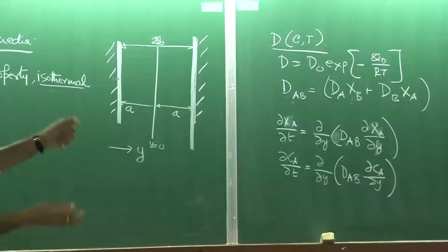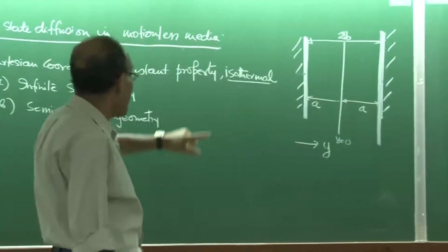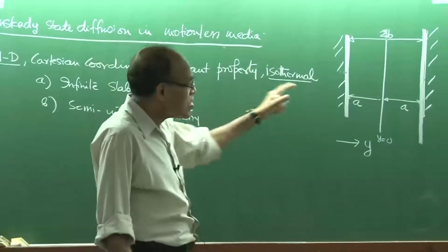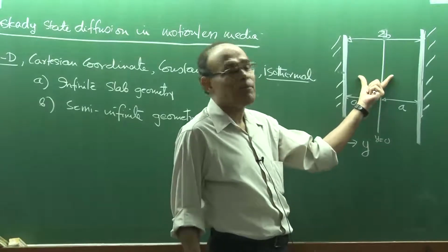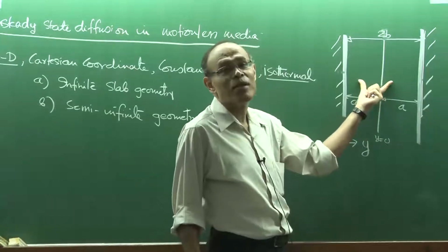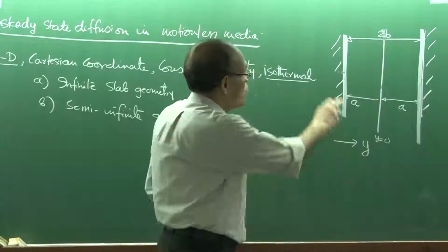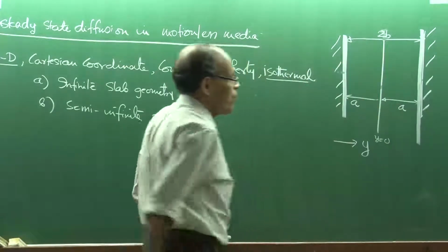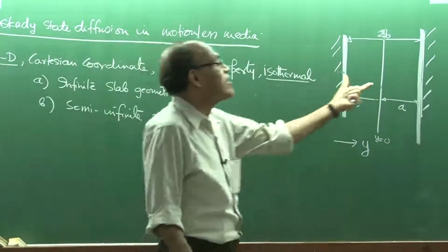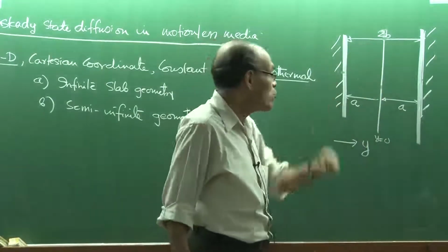So therefore they could be interlinked also. But in this particular problem, because it is a single phase problem, it is just one single material, it could be iron, it could be copper. There is no interdiffusion, so there is a species which is diffusing through the solid. You can take that this is steel and carbon may be diffusing.